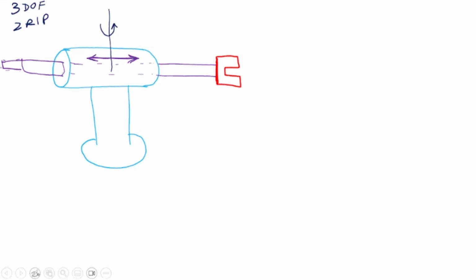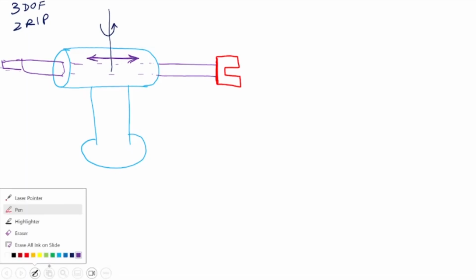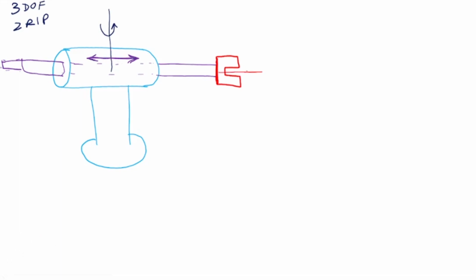Now the third one, which is the red color, is a rotating joint again. So this one can rotate about that axis. It's like a roll motion. So where are the 3 axes? Let us put the axes. First we understood that there are 2 revolute joints and 1 prismatic joint. Then we have to put our z axis. Z axis is the axis of rotations or translations.